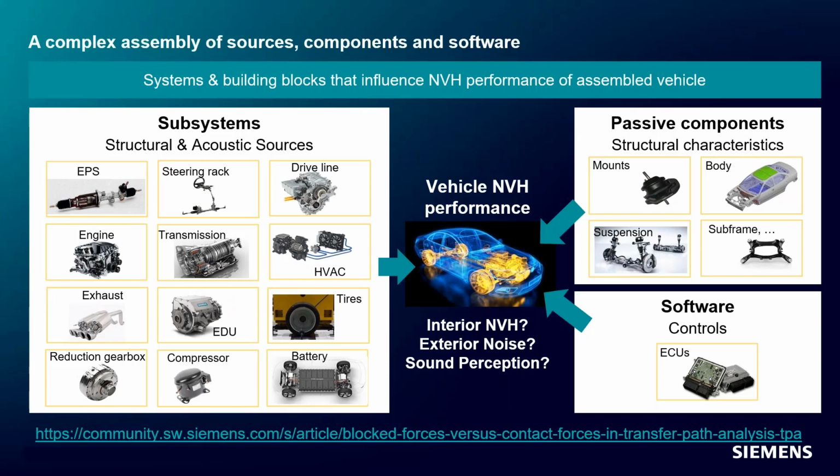In virtual prototype assembly, we characterize sources and receivers independently. Actually, no physical prototype is needed. The active component is characterized by invariant loads, what are called blocked forces. Blocked forces are the forces that characterize the strength of the load from the source, independent of what it is connected to. If you take the context of an engine mounted to a subframe, there are forces going from the engine to the subframe, and those are called the contact forces.